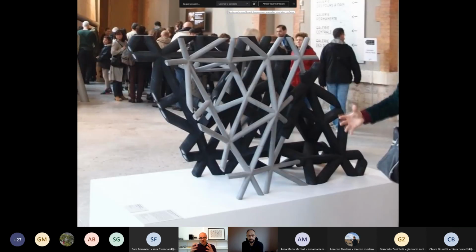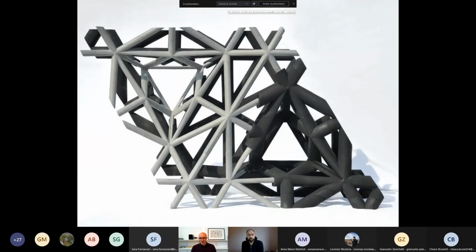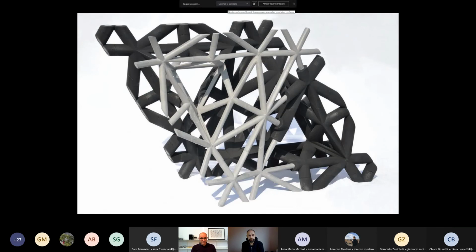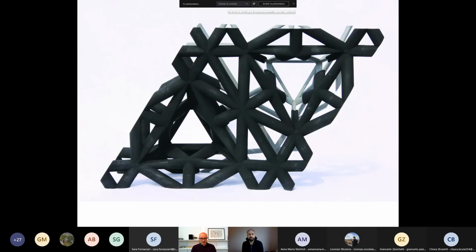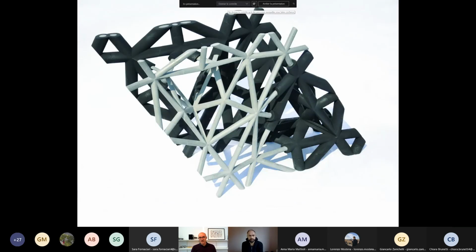When you remove it, you have this lightweight concrete structure, extremely lightweight. Just to give you an idea, in this structure, which is 1 meter 65 in diagonal, or even 1 meter 80, the length of the diagonal, we used only 34 liters of cement, or 44 liters.